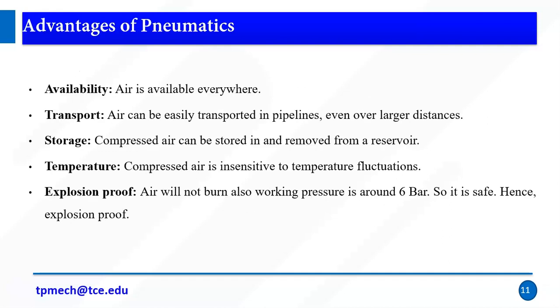So what are the advantages of pneumatics? The first one is availability. Air is available everywhere. Transport: air can be easily transported in pipelines even over a long distance. Storage: compressed air can be stored in and removed from the reservoir, so we can easily store it in the reservoir. A reservoir is nothing but a storage device.